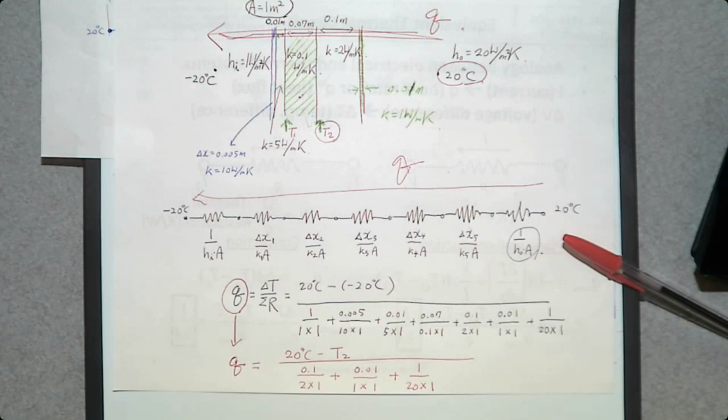There has to be a temperature gradient in the insulation to have heat transfer through it. Okay? So when I ask, what is the temperature of insulation, that question is wrong because it should depend on the location in the insulation, right? Yes.